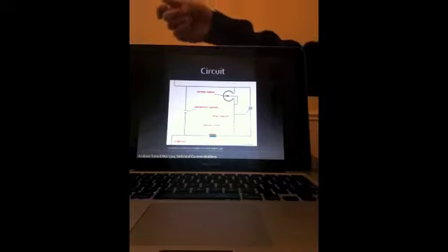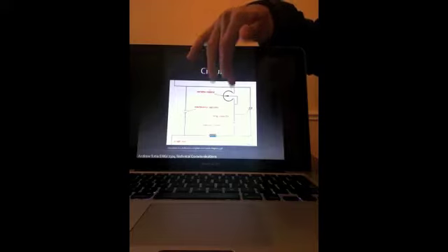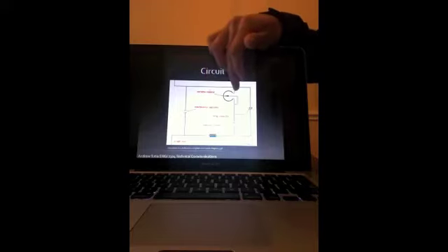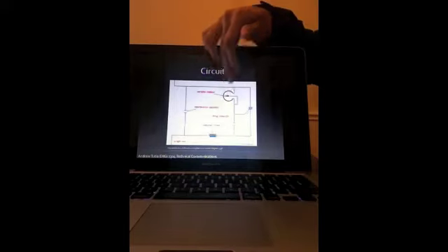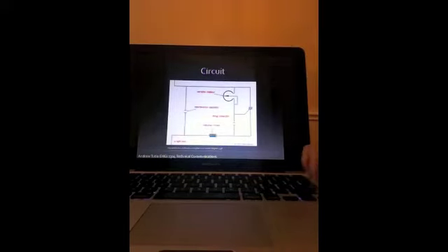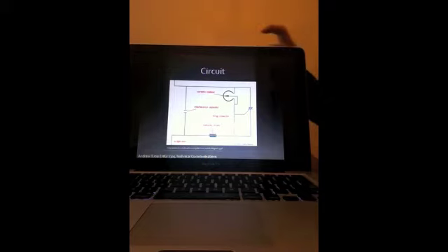As opposed to when the knob is turned counterclockwise, say for example it's over here, the energy will have to go through much more of the resistive material before being connected. Of course, the control arm is what is connected to the knob on the dimmer switch. So whenever you turn the dimmer switch, you're actually turning the control arm on the variable resistor.